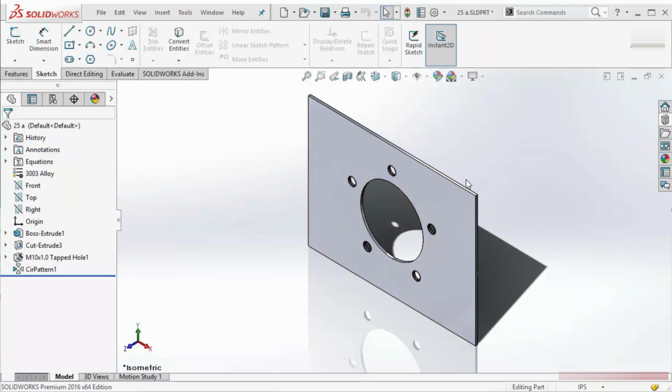One more important thing I will mention about rotation. Let's say I want to rotate this part based on this line. You can do that. You have to press your middle mouse button one time after hovering over this line. When I hover on this line, next to the cursor we can see there is one line. So I just have to press the middle mouse button one time, and you can see this is showing a rotational icon, but this is slightly different.